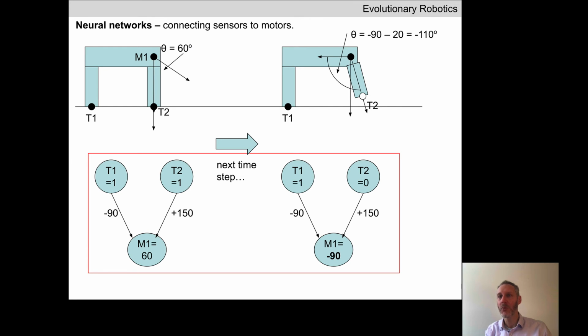It should swing outward more, possibly, because there is inertia and momentum in the physics engine, which we haven't talked about so far. So if you have a heavy object like this front leg, in which torque has been applied to start to accelerate it forward, if a new torque is going to be applied that tries to rotate it in the opposite direction, we have a negative difference now, which means we're going to apply torque in the clockwise direction. The leg is not immediately going to respond and start moving in the opposite direction at the next time step.